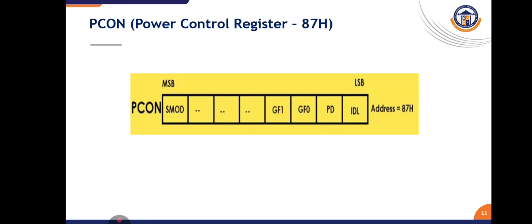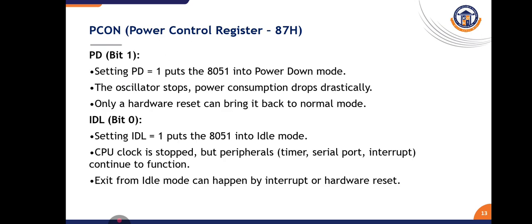As I said earlier, during idle mode, the microcontroller will stop the clock signal to the ALU, and in power down mode the oscillator will stop and the power will be reduced. For this purpose, the PCON register is used.